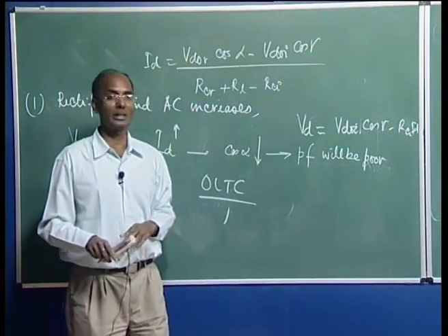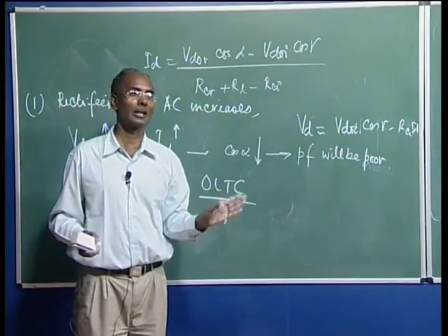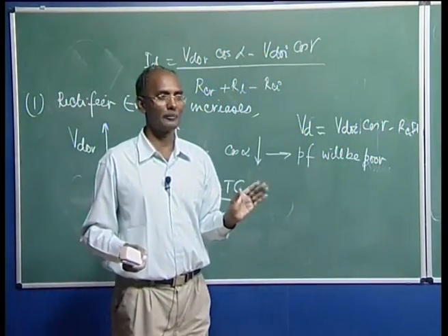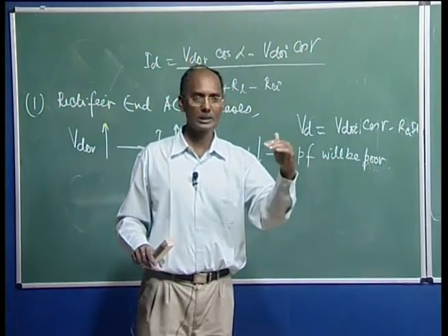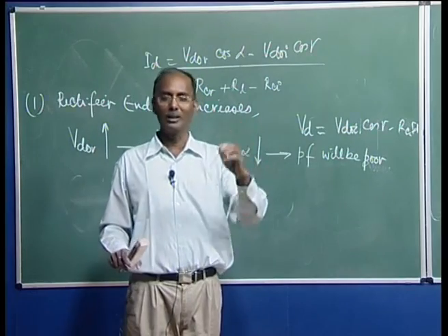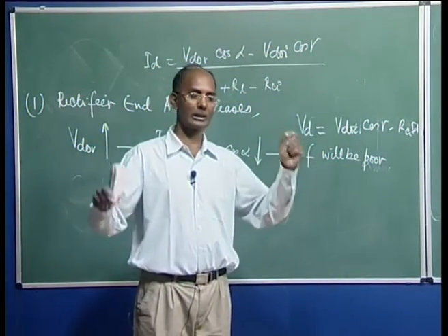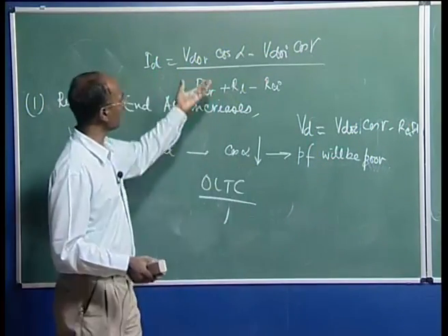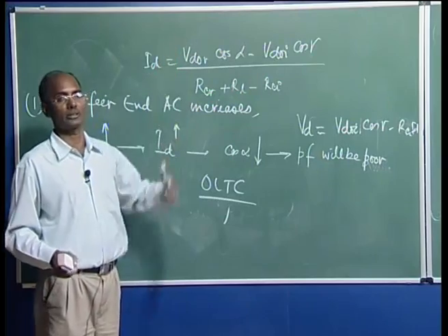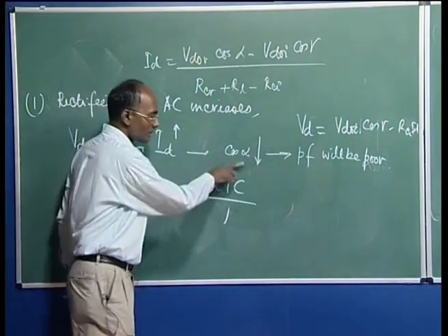Now the question is, if it is still not maintained, the voltage increase cannot be more than 5 to 10%. If it happens, your line will burst first, the AC system, because if it is, let's suppose, 400 kV, the voltage cannot be more than 420 kV, because there is another AC system that will be over voltage and everything will be tripped. So even from here itself you can adjust this voltage. So now you can see this.